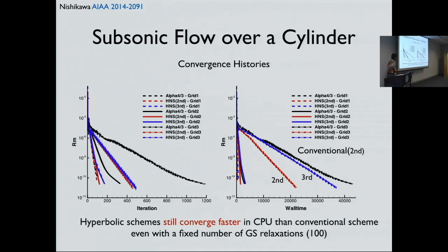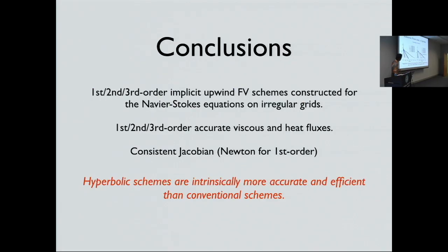So here's the convergence. Let's focus on the wall time. The maximum residual, this is the maximum of the L1 norm of each equation, versus the wall time. We want to find a 3. For the third order, all these 100 relaxations are probably not enough. This convergence is really awesome. But the third order convergence is a little bit faster, this one. If I define a finer mesh, I expect this converges much faster.